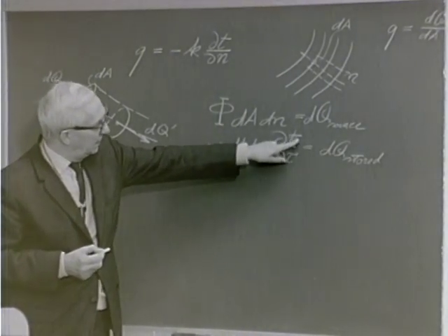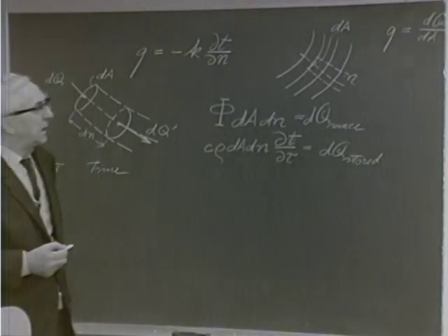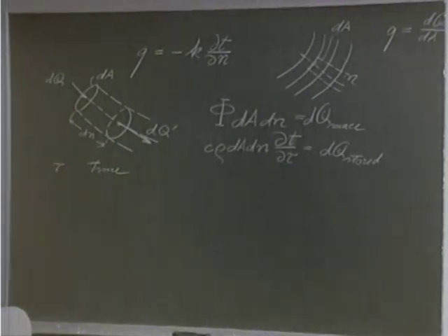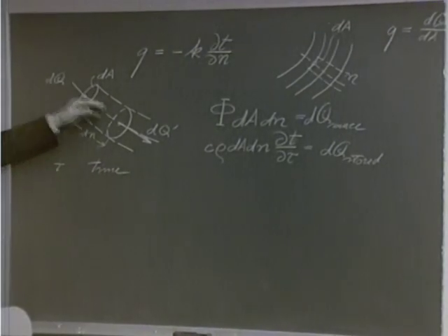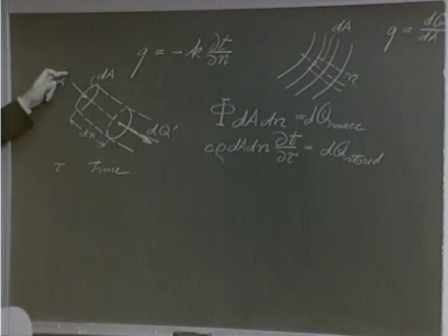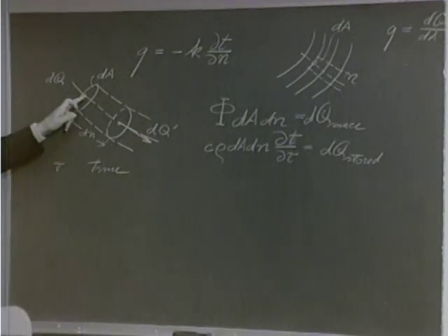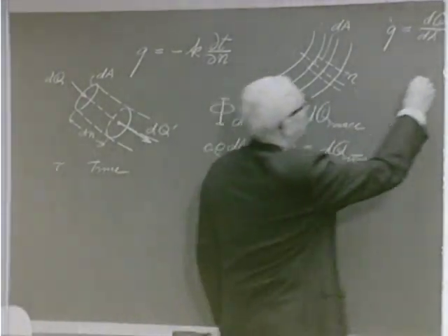This means we are only interested in the change of the temperature with time, not in the change with location. Okay. And then now we can write our heat balance. Obviously, all of the net heat which goes in and which has to be stored in the interior of our volume element will be the following. By heat conduction, we get into our volume element dQ minus dQ dash.